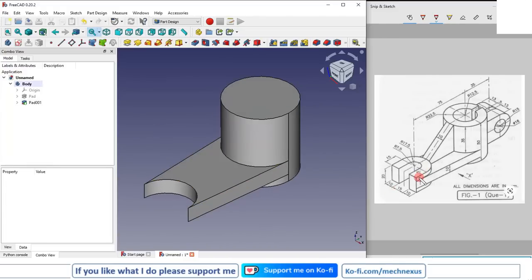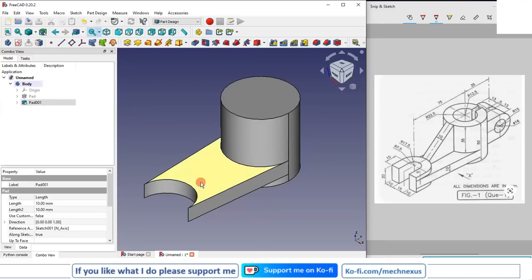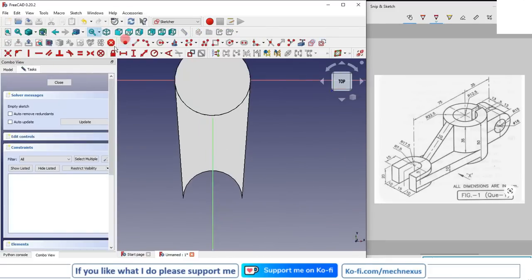Now I will create this one. So for this I will select the face and create a sketch. I will project this arc and from the center it is a 15 mm. So I will select the 3-point arc. Here is a conflict, I will delete it, and from the center it is a 15 mm, so I will select the line.